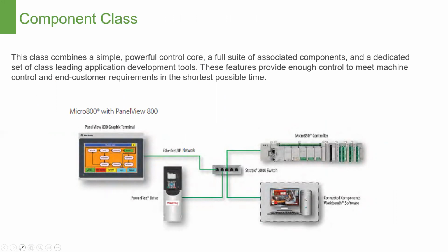Once again, the PanelView 800 can be connected to a MicroLogix and, I think, the L1 and the L2 CompactLogix, so you can use it outside of the Micro 800 family if you want. But it's intended to be a small machine level control, somewhat simple display, shall we say, for your machine level control.